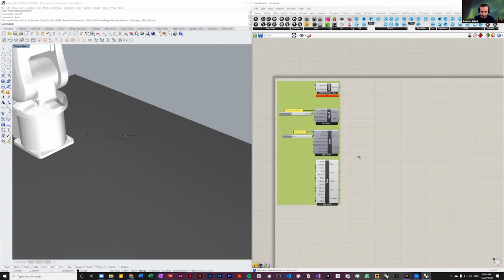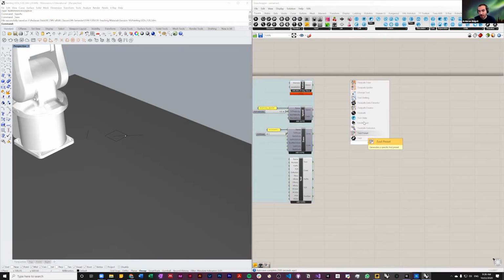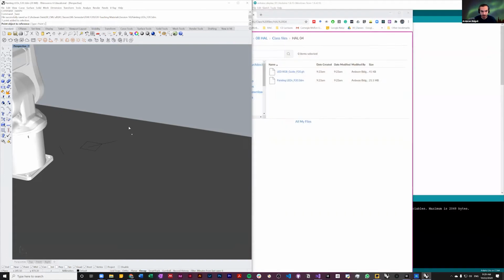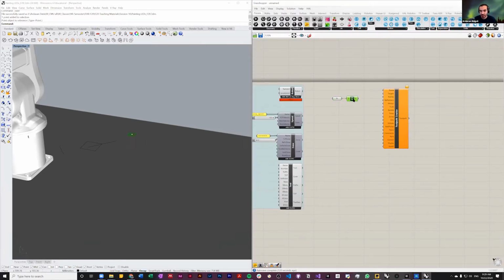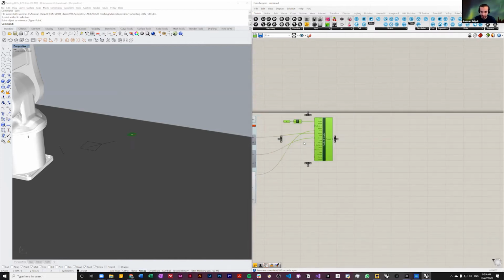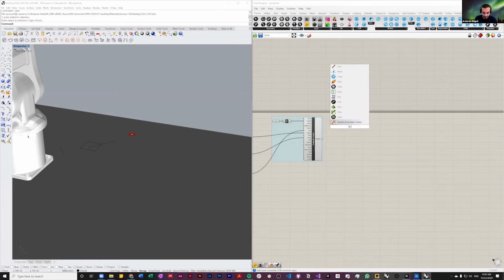No problem. I'm going to keep the toolpath here, the toolpath creator. Where's that? Okay, here. And I'm going to make one blank target here for now, like an XY plane that connects to this simple point here, and set one point. Good. This is my target, and it uses this speed value, this zone value, and this tool. So far, so good. I want to make the IKSolver, so I'm going to make it another group. I want to have the IKSolver.